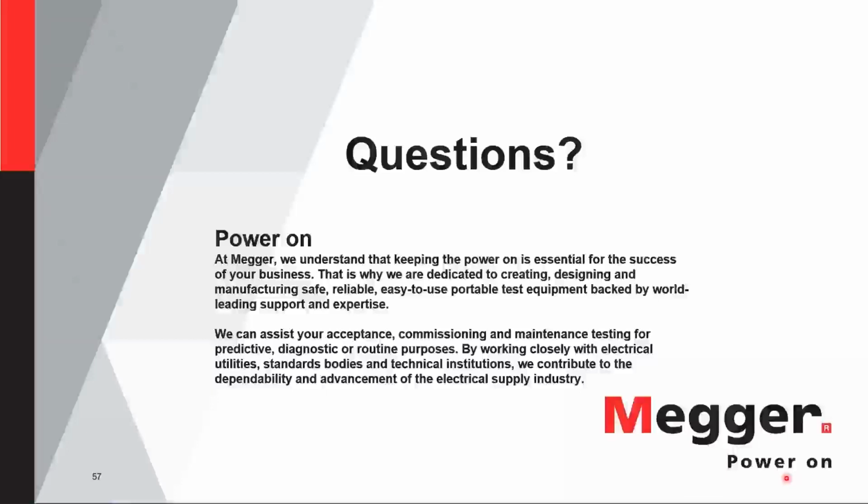A lot of utilities have been doing the ASTM D877 test, and because of all the historical data that they have, even though the ASTM D1816 test is the more preferred method for insulating liquid in transformers, a lot of times utilities may not switch to ASTM D1816 because they have some history with the D877 test. So again, as I said, it depends upon what the practice is.